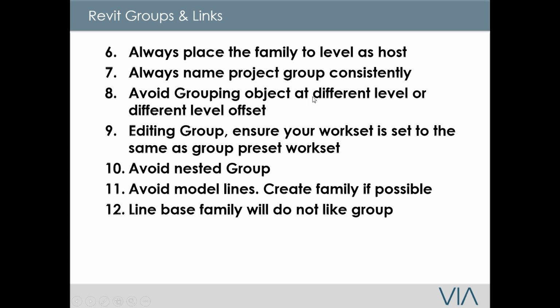Avoid grouping objects at different levels or different level offsets. What I mean by this is that if you have furniture in level 1 and furniture in level 2 and you group them together just to make one massive group, you pray that these two don't change in height. Chances are, if that level ever changes, it will ungroup your group or tell you to fix it.